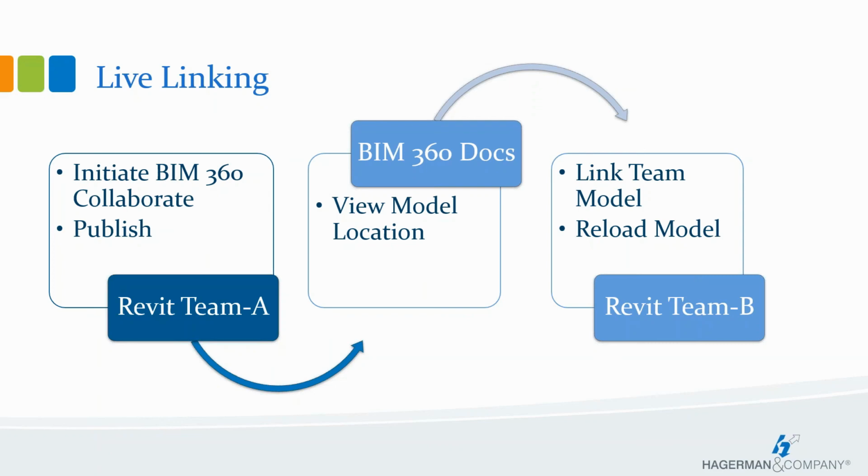Periodically, you'll want to reload the linked model to see updates. An advanced user may also want to enable copy monitor between the host and the model. And the work shared Revit model is only accessible through Revit. Project members will need view permissions to team folders. Okay, so the one shortcoming on this is that you have to give other teams access to your team's working folder. View only permissions, but they do need to have permissions.